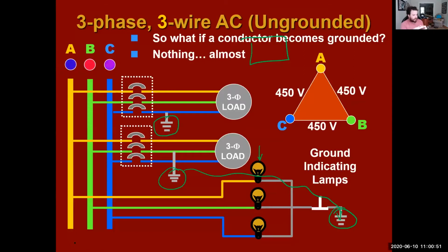Now you can try and find the ground in that room. What you would look for is, you would pull open all the lights and look inside the lights and see if anything was sparking in there, if any grounds like that. If you check through everything in that room, basically what you would have to do is eliminate where the ground could be.